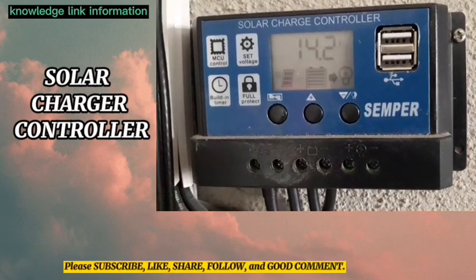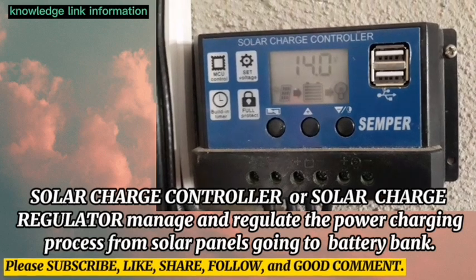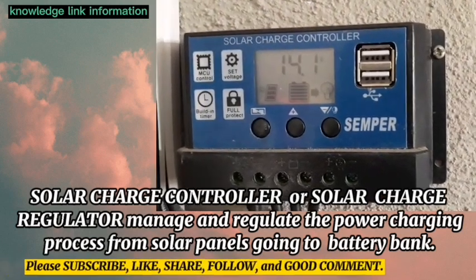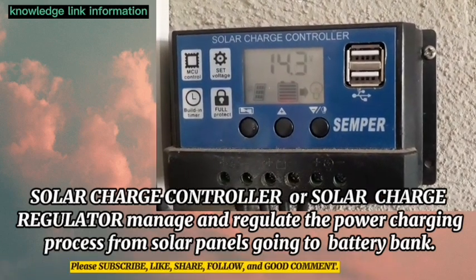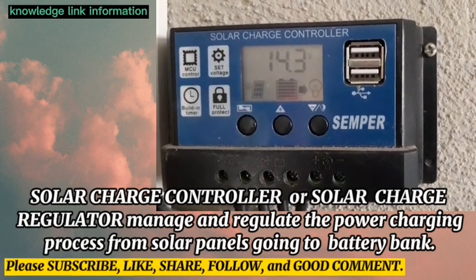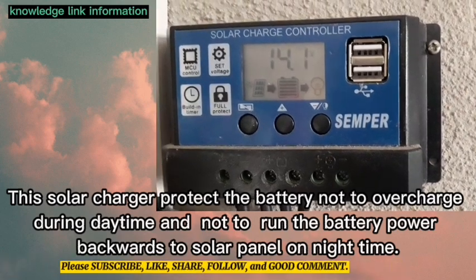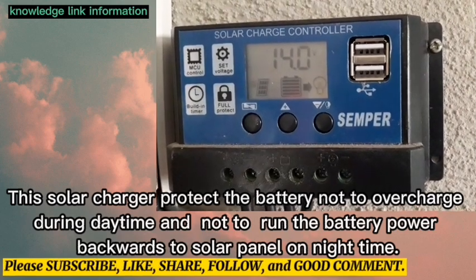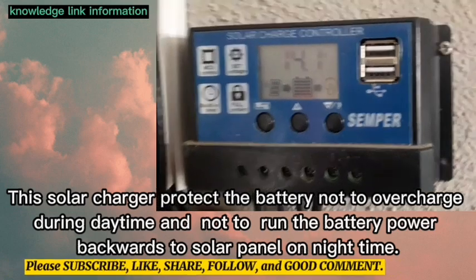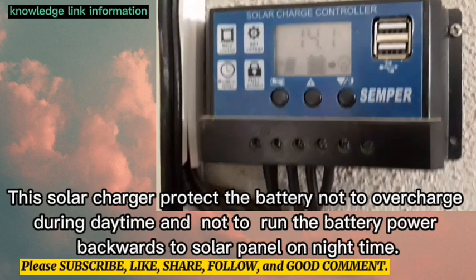Solar charge controller. A solar charge controller, or solar charge regulator, manages and regulates the power charging process from the solar panels going to the battery bank. This solar charger protects the battery from overcharging during the daytime and from running battery power backwards to the solar panel at night time.